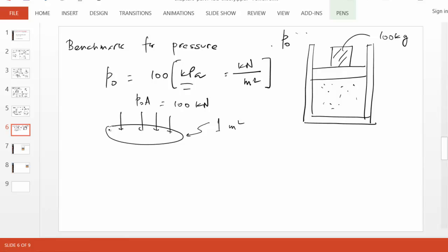Whereas we can say, wait a minute, I can hold the plate without any problem, even though there are 100 football players on top. That's because there is 100 kPa, or 100 kilonewton of force, from the bottom. So all you have to do to hold a plate is to support the weight of the plate, because the atmospheric force from the top and bottom cancel out.